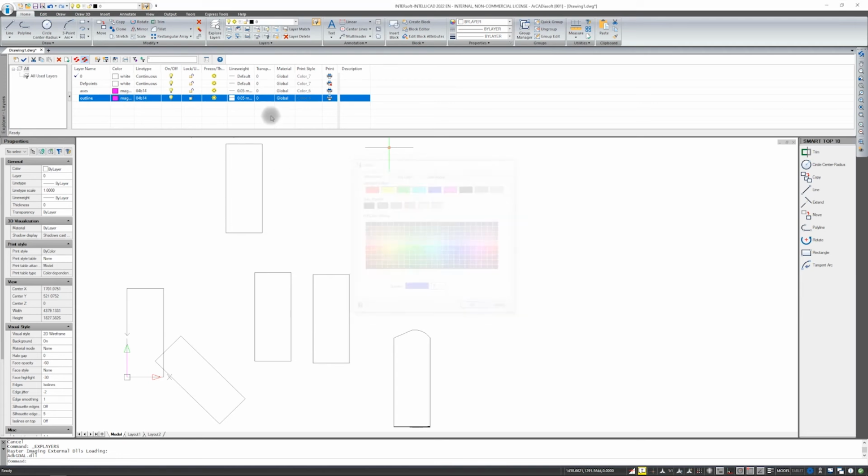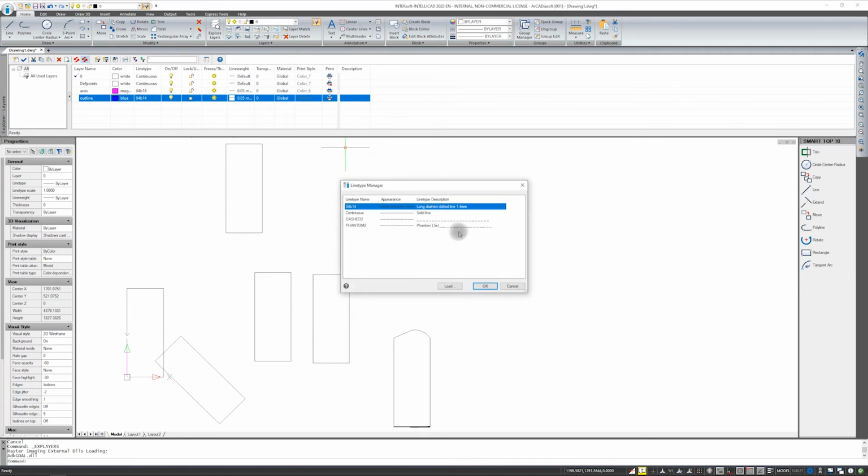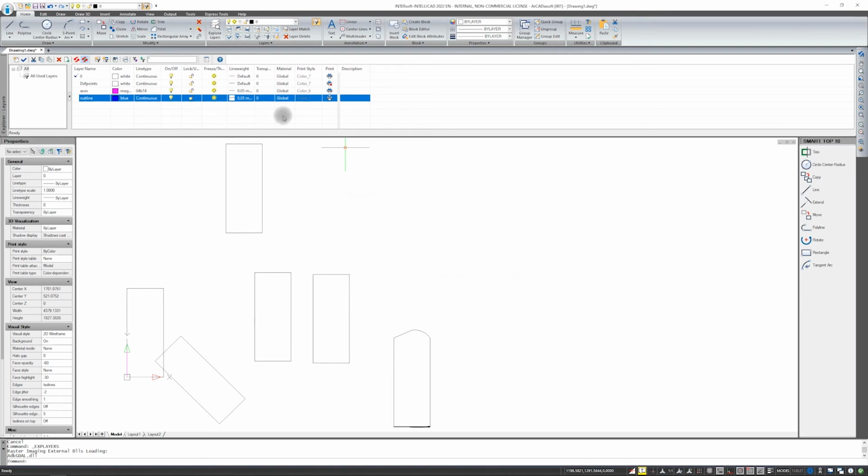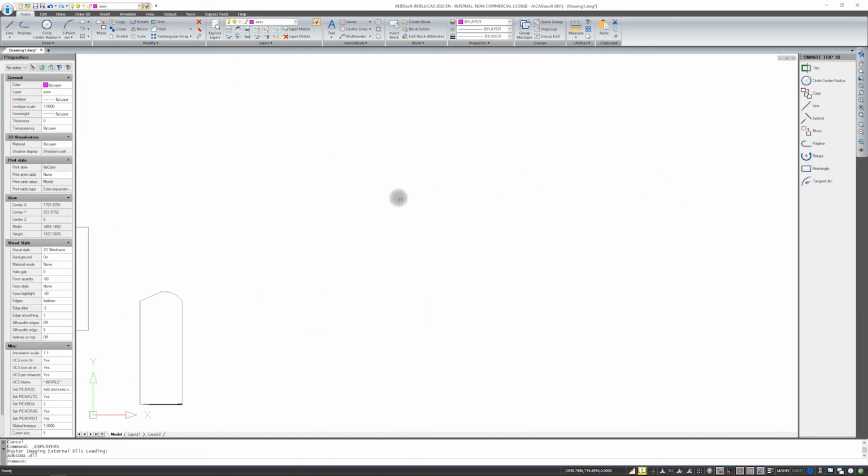It will definitely be elements drawn with a continuous and thicker line. I have it turned off down here in the status bar. In the status bar, there's an option to turn on and off the thickness, but I have it turned off. But if there was such a need, you can turn it on at any time. Now the layer that will be active, which means the one on which I'll be drawing. I double-clicked it. These will be the axes.